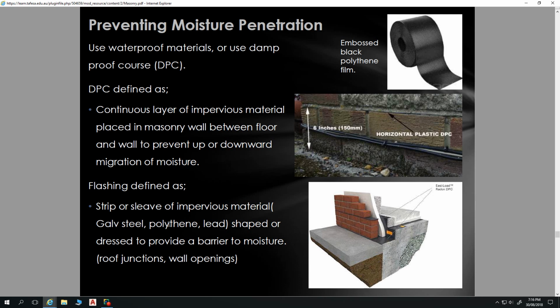The old way of doing that was with what are called clinker bricks, which are double fired. So it gets fired once in the kiln and then goes back in and gets fired again. They end up being incredibly hard, but slightly more brittle bricks. But they're very hard bricks, and they're good at stopping moisture coming through.